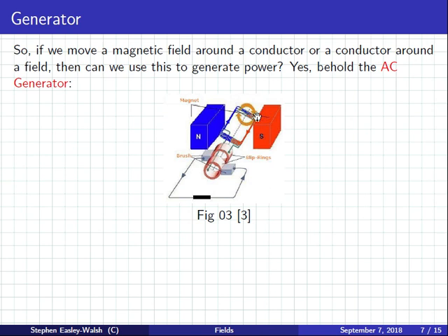You take the motor and you turn it, and as you turn it, you get a current. So you can power a resistor, like the light on your bicycle. Now the big difference between the DC motor and the AC generator is there's no commutator. Instead of the commutator, you have slip rings.